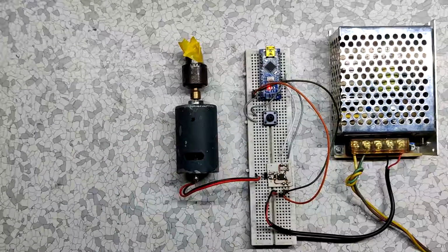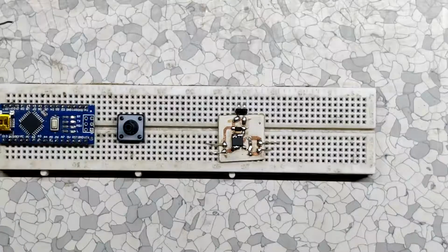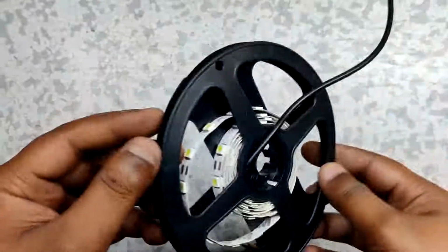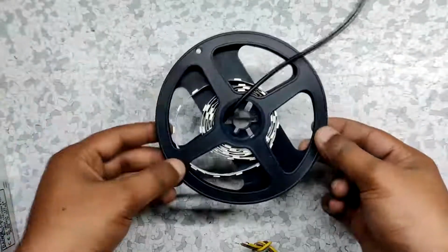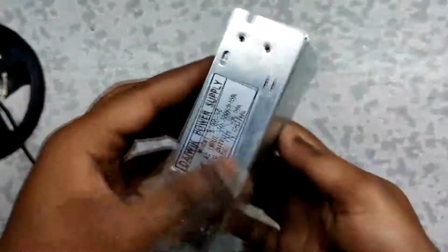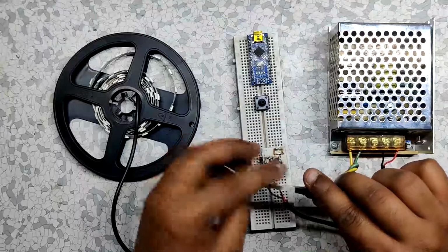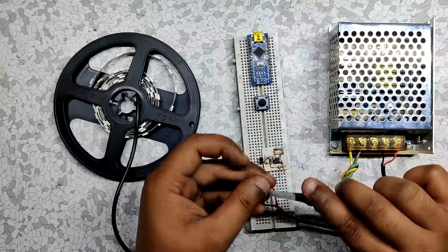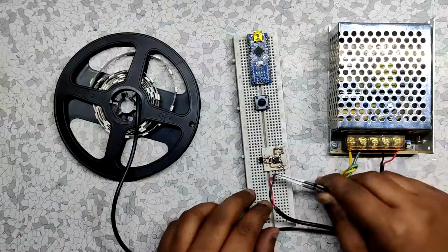Now let's connect this setup with the MCU and control a load. Our load will be this LED strip which has 9 volt 1 watt LEDs in parallel. This setup will be driven by this 12 volt 5 ampere SMPS. We connect our DIY breakout board setup with our load and MCU in this arrangement.